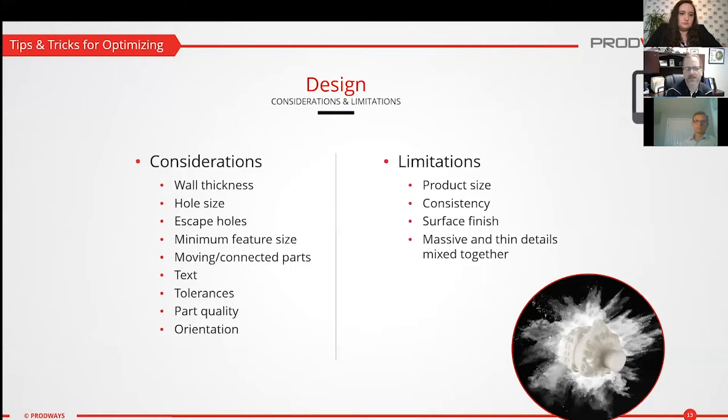This technology may not be the best, and really there's not many 3D printing technologies for massive sections, heavy sections. But the nice thing is there are different settings for each type of part, and you can change those settings within the same build. You have a heavy, massive wall part, you have very thin-walled, small detailed parts. They can be run at different settings in the same build, which is a big advantage.